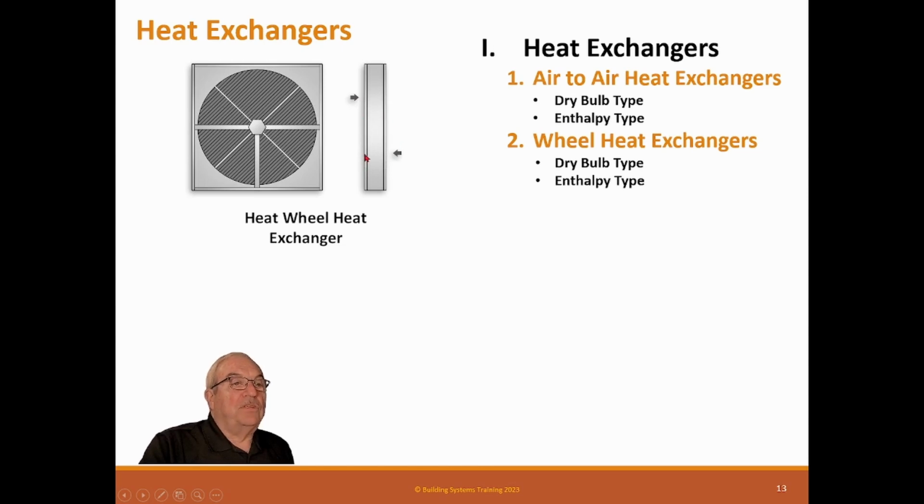If you have both these flow in the same direction, then what happens is the wheel gets impacted with debris. This way, this air will blow it off. If this has debris in it, like lint, and it sticks to the wheel, this will blow it off. If you don't do that, have the same way, this wheel doesn't last long before it gets clogged up.